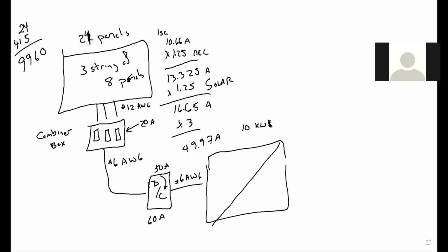Okay, so we're fine, right? Not a problem. In fact, what we would find when we look at the spec sheet is if this 10 kW output is probably capable of taking in like up to 13,000 watts of DC in, that's using clipping to have 10 kW going out. We can double check that spec, but we're certainly fine because it's even less than 10 kW. All right, so that's all right. We've already sized the voltage of each string so that it's not going to exceed. So the input there coming in, we're all fine.